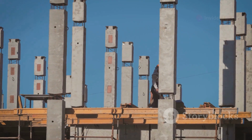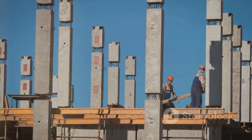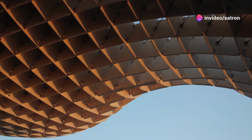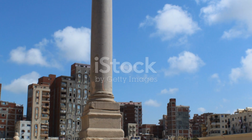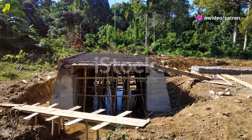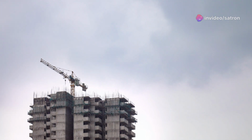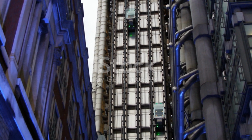You'll often see W shapes used for columns, just like beams, but you'll also encounter something called HSS, which stands for hollow structural sections. HSS are basically big, hollow tubes of steel. They're incredibly strong in compression because the material is distributed evenly around a central axis. Think of it like a soda can. It's much harder to crush it from the top than it is to bend it from the side. So whether it's a W shape, an HSS, or even a concrete-filled tube, columns are the unsung heroes of the structural world, silently bearing the weight of our built environment.